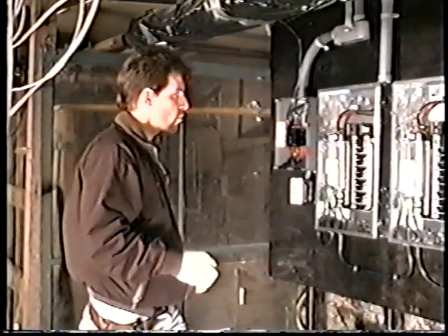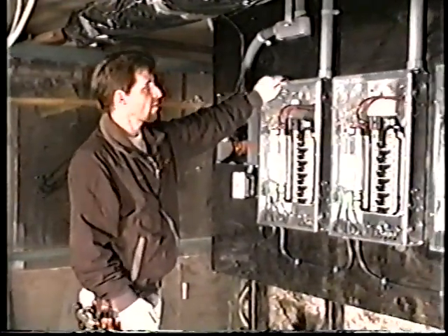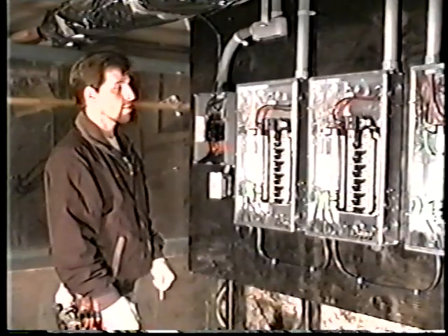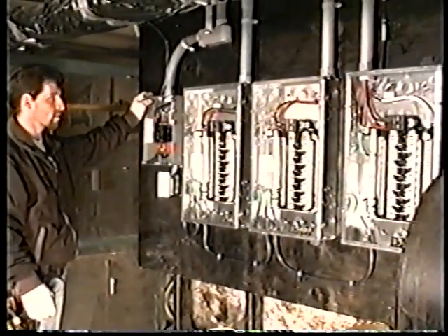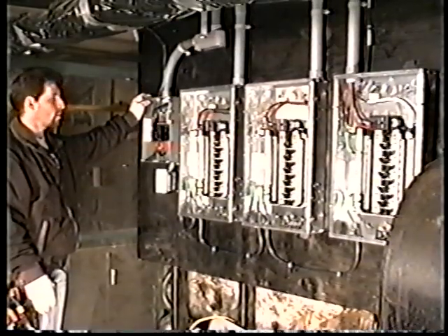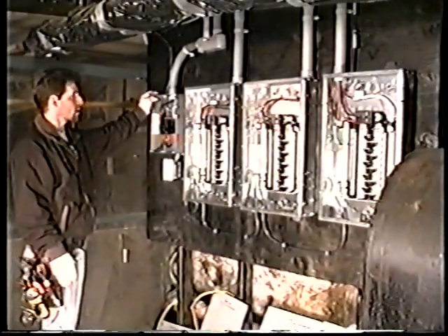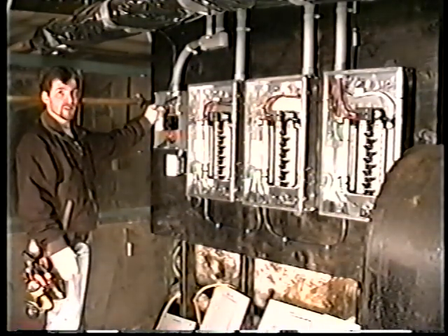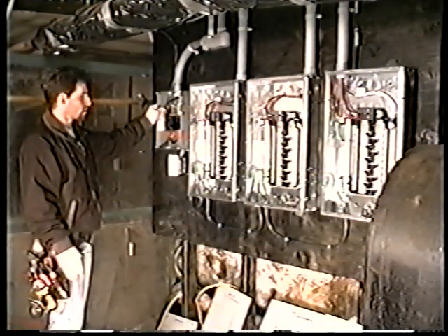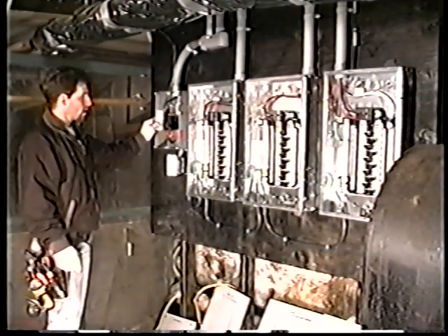We're going to install these new wires into our new services over here. We have 3 identical panels, one for the 1st, 2nd, and the 3rd floor, which are powered by the meters outside, and we also have a 4th little panel box, which is called the owner's panel, which is going to have all the outdoor lighting, basement lighting, anything for common area. These panels here, most inspectors only want 4 to 6 circuits installed, so people don't install another apartment into the basements or something like that.